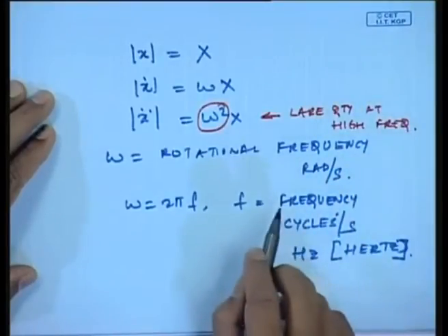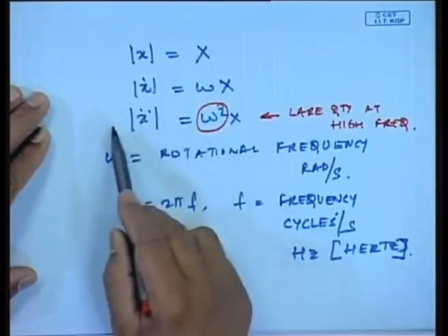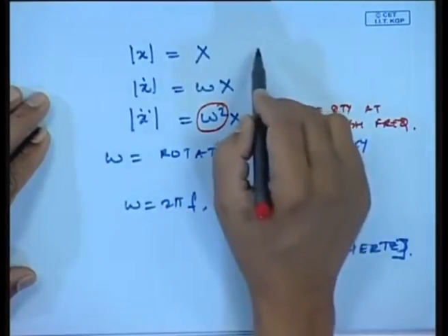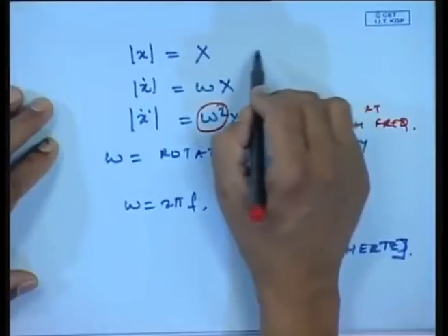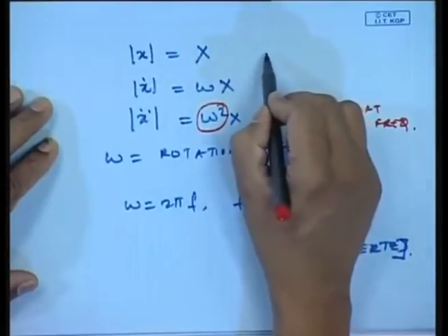So, it is always advisable to measure any high frequency vibration as acceleration, and for low frequency, like a shaft rotating at less than 1 rpm, 2 rpm, just to measure the static runouts or dynamic eccentricity, etc., we can measure displacement.